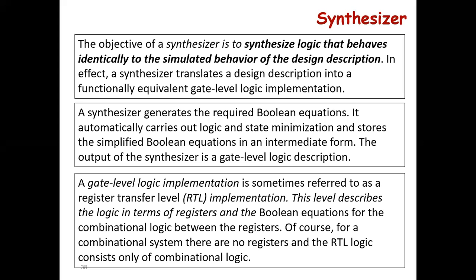A synthesizer generates the required Boolean equations. It automatically carries out logic and state minimization and stores the simplified Boolean equations in an intermediate form. The output of the synthesizer is a gate level logic description.